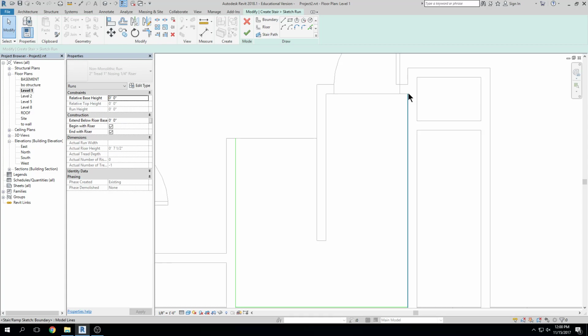I would say, in general, most residential stairs will be framed and they'll go from wall to wall, no gap, right? And then the railing will sit on the wall to help you circulate. If you have a metal staircase or some kind of showcase staircase, then it will likely be held off of the wall, right? It circulates up through the stair shaft, not resting against it. If you're in a commercial application, likely your stairs are going to be metal, or they're going to be, like in our case, concrete here. They may not touch the wall, right? But you can't have them further than 4 inches away from the wall, for safety. So there's not a really good answer other than it's just how you design it.